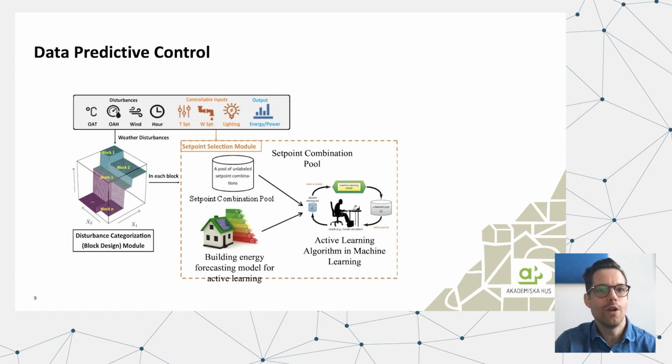The entire process is fully automated, but in this process it is based on manual work for sending control due to a temporary firewall restriction. So every 3 hours, new set points are determined using this AI-based supervisory control tool, including feature selection and active learning procedure. The air handling unit supply air temperature is between 15 and 19 degrees C, and hot water to radiators supply between 22 and 42. DPC was tested and fully implemented on October 22nd and November 7 and November 8.